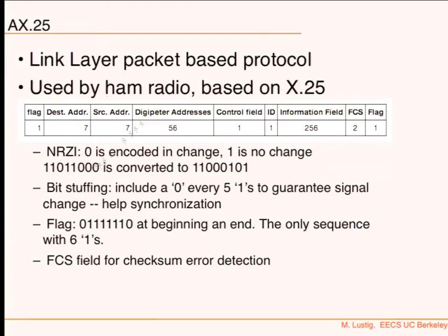It is based on AX25, and it has a very particular packet formation. First of all, it starts with a flag. I'll explain what the flag actually is. The flag is 8 bits, that's the number of bits, so 1 byte for a flag.